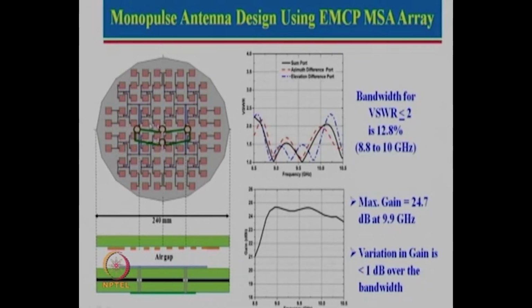Now as we mentioned earlier when we were talking about a linear array, if you use uniform amplitude, side lobe levels are relatively high, minus 13 dB. But here what we have done is we have taken power from the outer one, which gives this. So this actually provides an amplitude taper, the center is maximum and it goes down, and this particular array also gives us a reduced side lobe level.